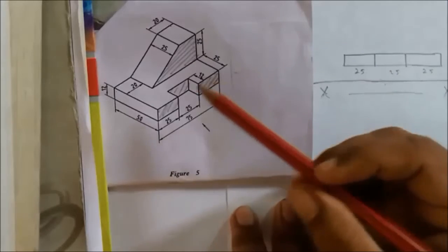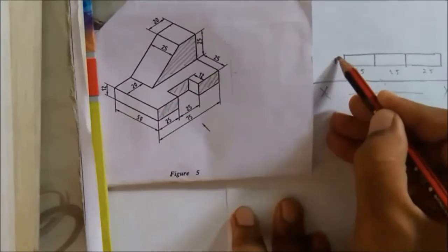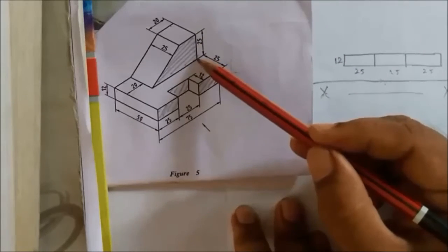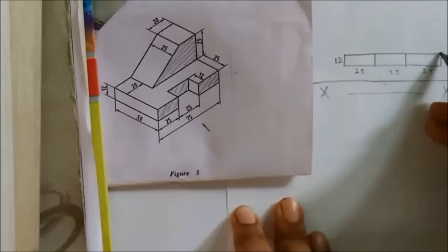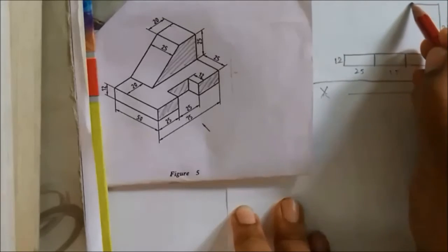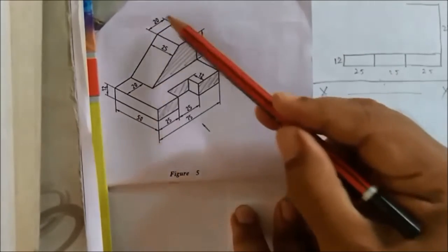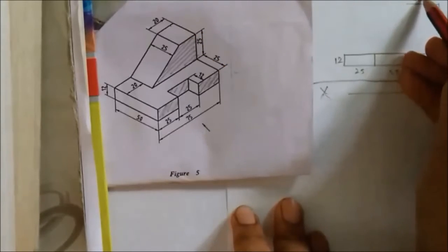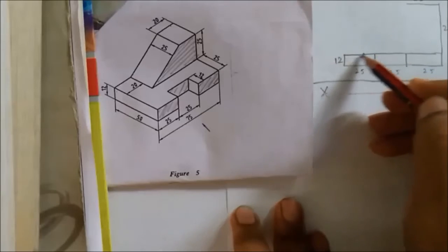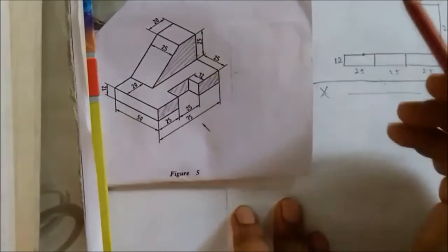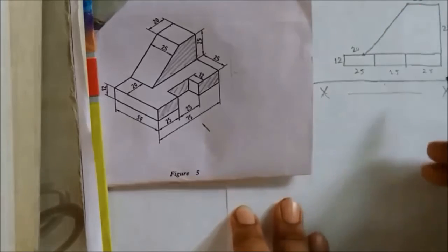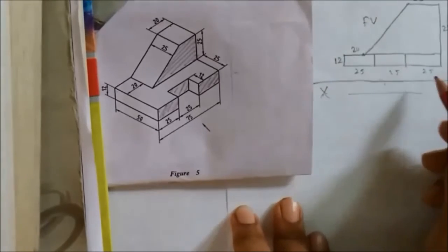And the height is, here it is given, 12 mm. So this is 12. Now you see this height, 25 mm from the upper face. So after 12 you draw a vertical line. This is 25. Now you draw a horizontal line. This length is 20. This is 20, it means this is also 20. So you take 20 mm and you take a point on this horizontal line. So this is 20 mm, so you take 20 mm from this corner. Now you join these 2 points. So this is the front view of this object.